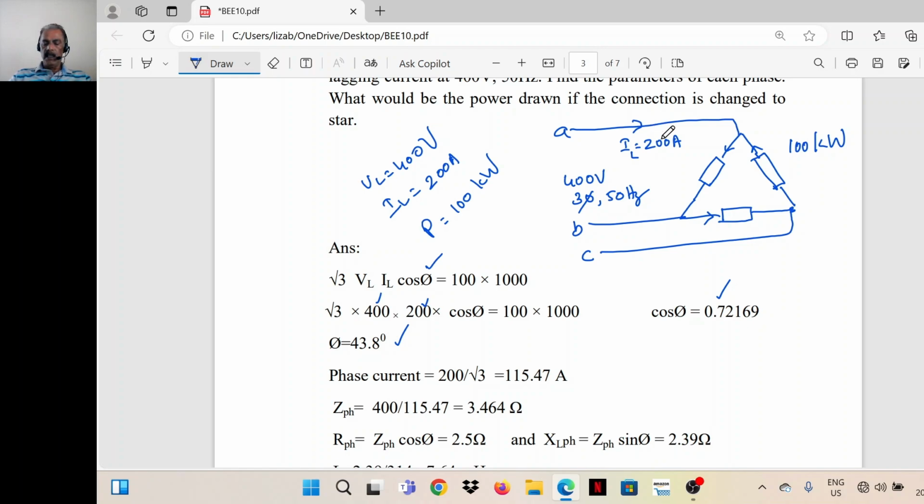Then here, the line current is given, which is 200 ampere. So it's a delta connected circuit. I have marked the 200 ampere only in one line because the supply is balanced and the load is also balanced. All the line currents will be equal. IA, IB, IC all will be equal, equal to 200 ampere. Then phase currents also will be equal.